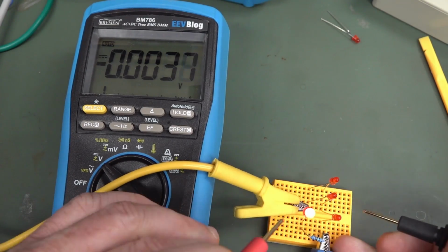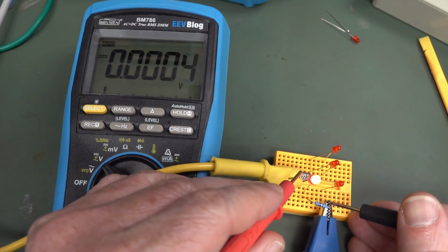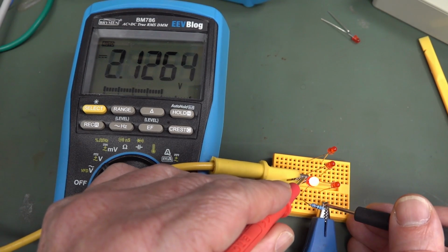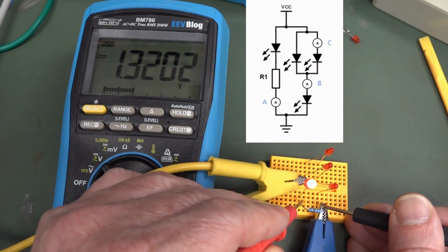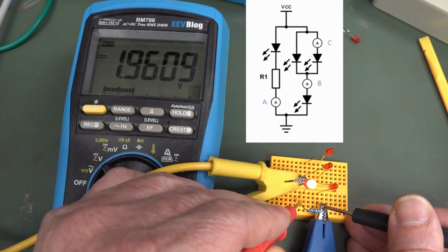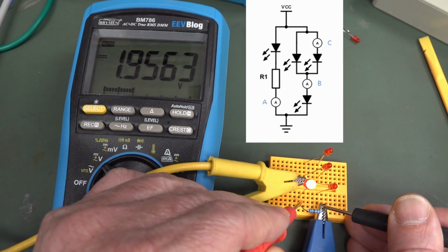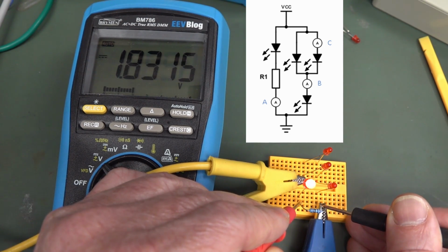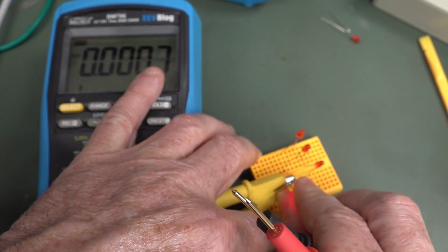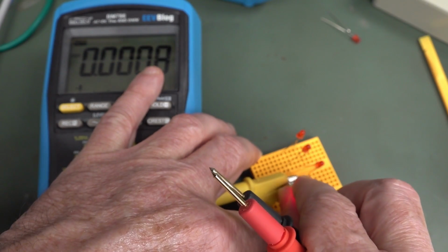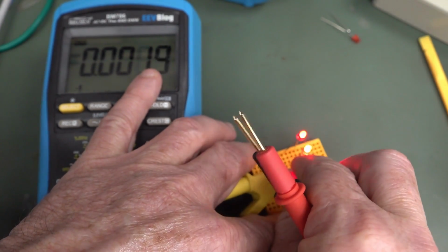Okay, so I've just got the single resistor on the left-hand side of the circuit. So that's our 4 volts input. And across the resistor, which is bang on 100 ohms, we have 1.96 volts. So I know 19.6 milliamps is flowing through there. Ohm's law, don't even need to get the current meter out for that. Now I'm going to move it over to put the other LEDs in series. Let's see what happens. I'm going to apply 4 volts.